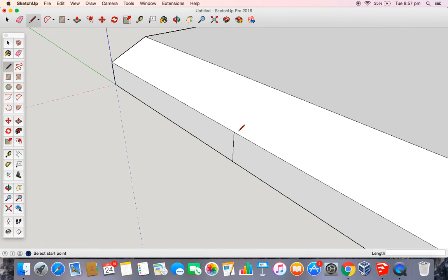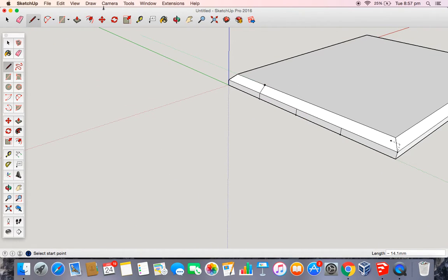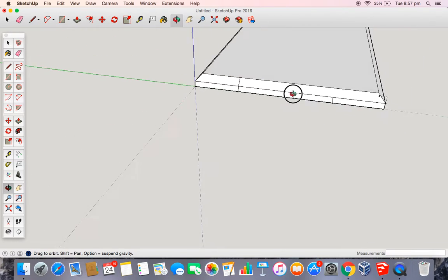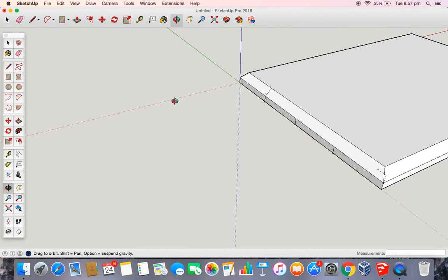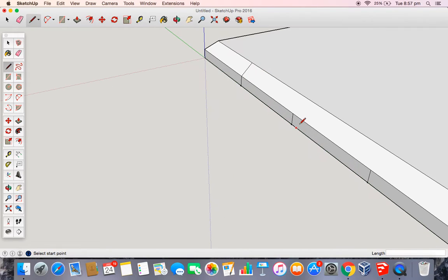Get our pencil tool and see how it's got a different color there? That should tell us that the line is going to be straight. So once I've selected on edge and it's got a different color, I can click and just check that that looks right. Yep, it's nice and straight. And just do that for the other two guide points and lines that you've drawn there.